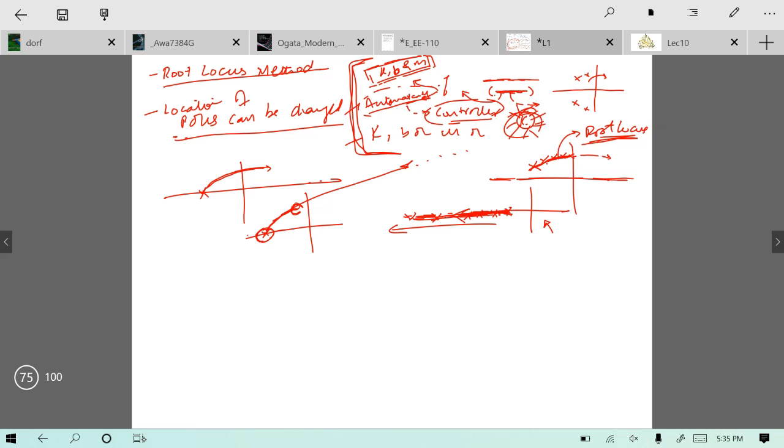So if your root locus is going to infinity, you can stop it from going to infinity by inserting a 0 over here, and your system will automatically become a stable system. Whatever the value of k you will assume, whatever the value of zeta you will assume, the roots will always lie within this portion whenever there is a 0 over here.